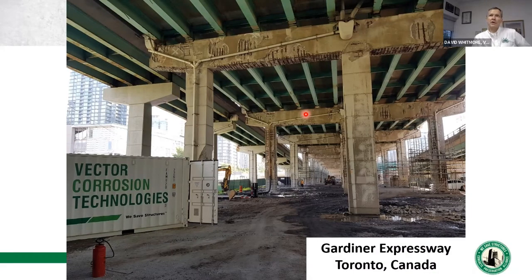It's showing the same concept. It's on a project that is going on right now. The first phase of it was completed relatively recently. What they're doing in this particular case is accelerated replacement of the bridge in question here. It's a long section of elevated expressway, very deteriorated because of chlorides. And in order to do this accelerated replacement, they are basically repairing and reusing all of the existing substructure, some of which is in horrible condition.